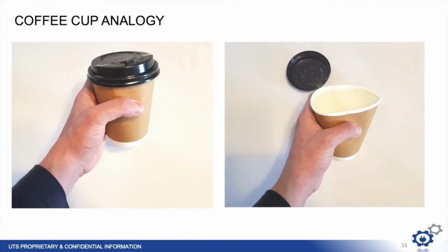The best way for me to think about it is imagining a disposable paper coffee cup. The lid holds in hot coffee and adds some rigidity to the cup, just as the crimped end of the can holds in the electrolyte and adds some rigidity to the capacitor. But if we start pulling or twisting on that lid, you would quickly come to expect that sooner or later there would be coffee all over the floor. Now, ultracapacitors are not so fragile as coffee cups, but a well-designed module can last 20 years, so it's worth understanding the potential problem areas. So now we know we have to protect the cell crimp.